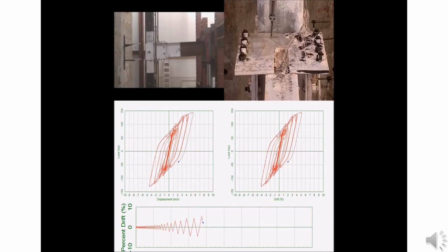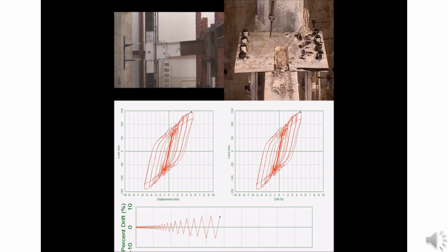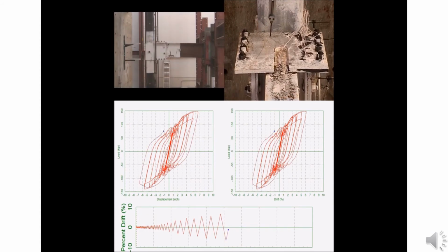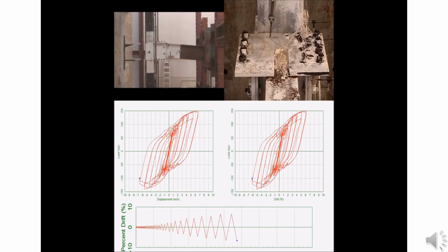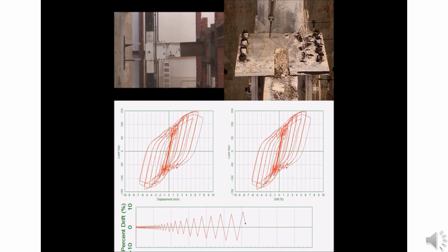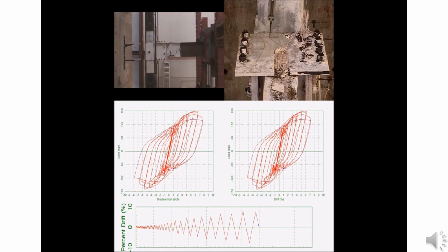Now you can see in the hysteretic curve that while the code requires a 4% drift angle, this connection went all the way to 9%. Recently, the latest resiliency compliance testing shows that SidePlate connections exhibit limited deformation at design level earthquakes. This has been independently validated based on the criteria set forth in FEMA P58, which is the current US standard for resilient design and risk assessment for both new and existing buildings.